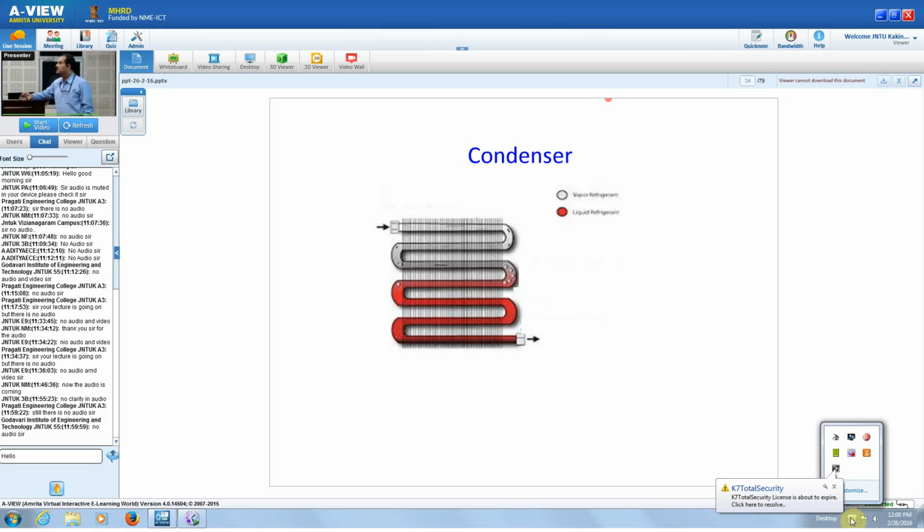It means that the load is very less. Or if the load is more, then maybe it will not form. Right? You have to provide more refrigerant. And if it is outside also, sometimes if the cooling is very high, then it will try to form ice. That is called frosting. Right?